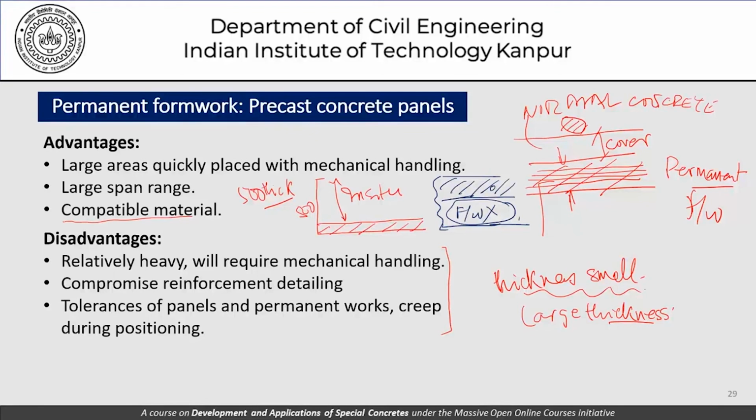Well, the spirit is the same, that in both cases what we are trying to do is improve the quality of near surface concrete. So of course in this case it's not only near surface concrete which is being improved, but one half of the member is being improved. It is expected that the performance of one half of this member will be very different. Of course, the 500 thick member will behave, or is expected to behave, monolithically, and that is something which the designers will take care of. So the designers will actually come into the picture when we are trying to use such construction methods.